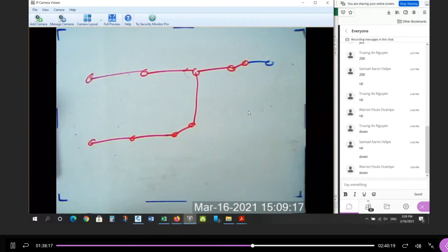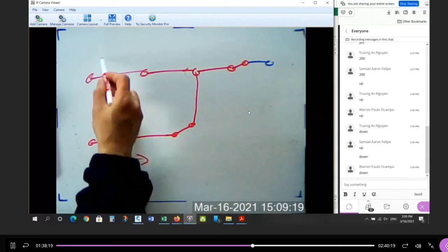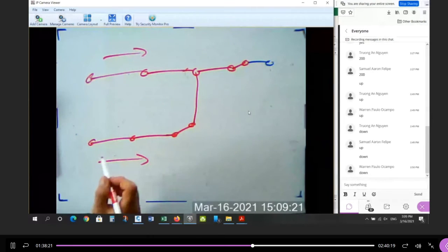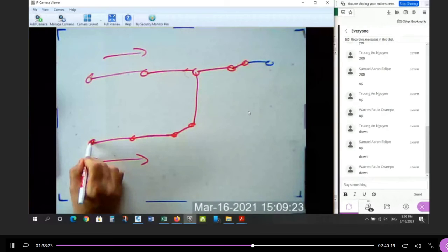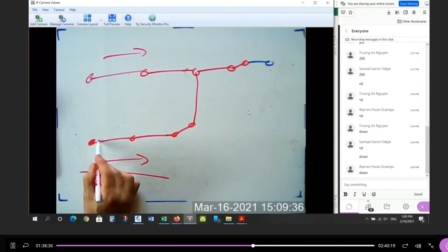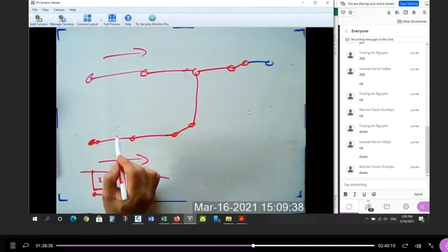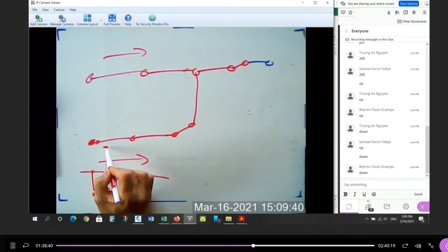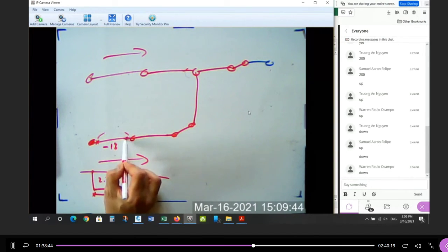Right? So what we're going to do is we're going to start at the top. Remember, these are all flowing this way, right? Coming out to here. So I'm going to find out what the elevation here is, right? And I know the road. I'm going to find out the elevation of the road. I'm down 2.75. That's the top of the pipe. Then I'm going to subtract the size of the pipe. And that'll give me the invert of this pipe. And then I'm going to go down at 1% for this pipe, whatever this distance is, to get this invert.